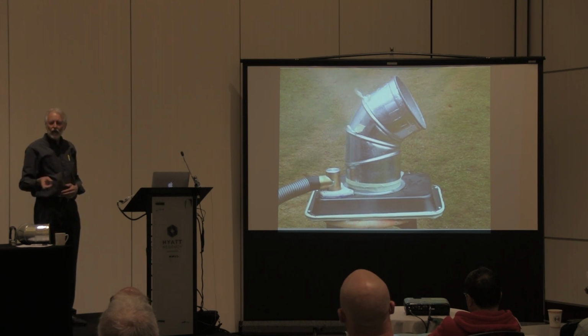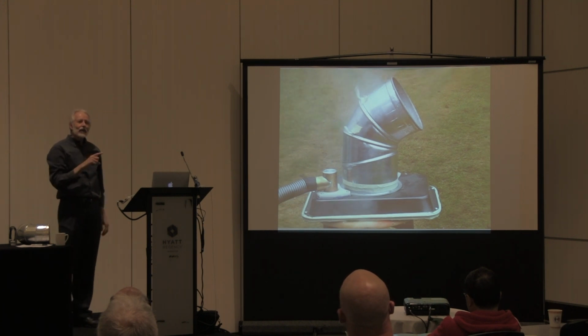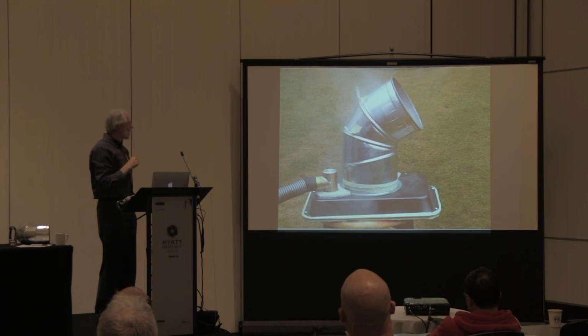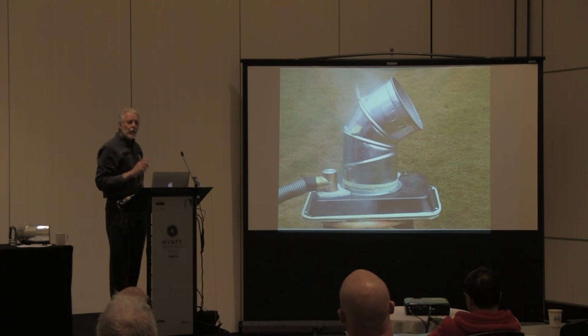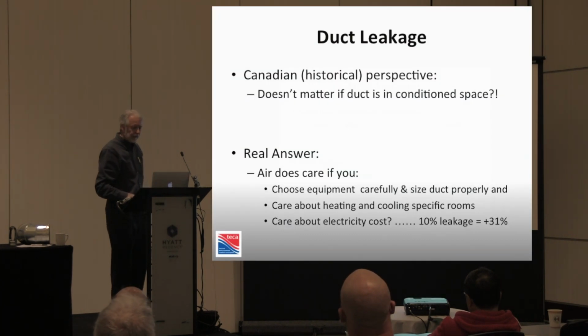In fact, once before we had the smoke generator, we used smoke bombs, and we thought someone was going to call the fire department. Smoke was just billowing out of the top floor. The theatrical smoke generator is a little bit more civil. But the bottom line is right now, if you are putting in a heating and ventilating system and you're starting to approach more correct sizing, you really, really, really have to start sealing up your ductwork. It's non-negotiable.